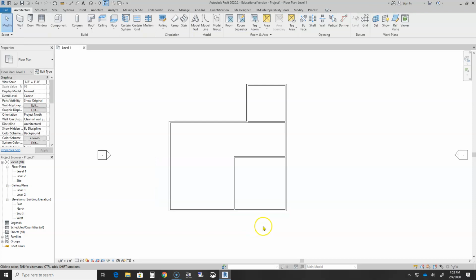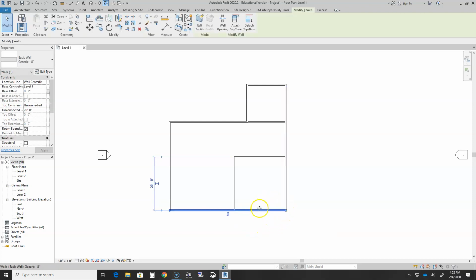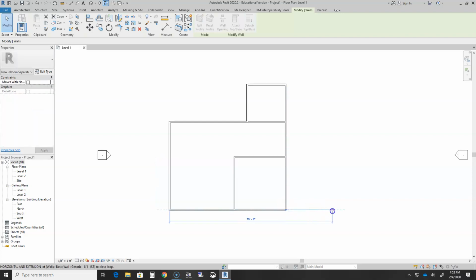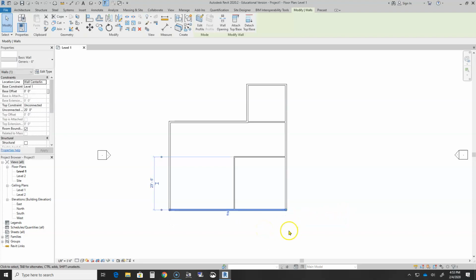And then we'll just move that wall down. And that's how you move walls. You just click on it and it tells you, just do this, move it. If it's connected to other walls, it'll stretch those walls along with it. If you don't want those walls to stretch along with it, then I'll show you something that we do later as we go to keep that from happening. And you can always pull on these grips down at the end as well and adjust the distance on that.